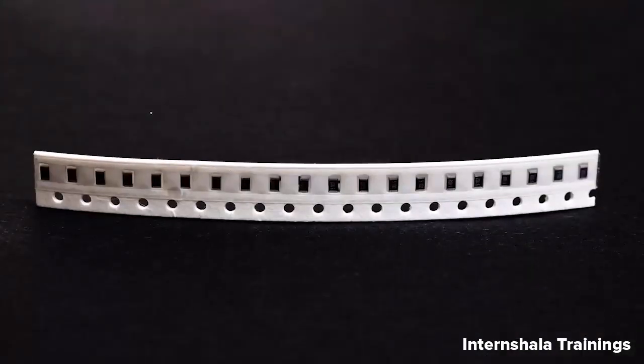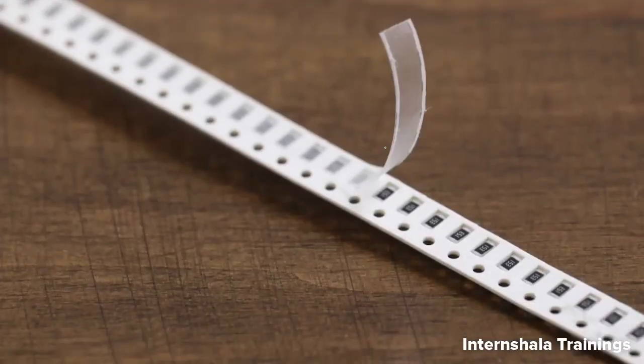After that, this is how you are going to receive the SMD resistors, and this is called cut tape. Why it is called cut tape, you will get in a moment. For example, if you order 20 or 30 quantity of SMD resistor, let's say 10 kilo ohms, this is how you are going to receive them. There will be a plastic film on top of this tape. You just have to remove this plastic film, and based on the requirement, you can take the SMD resistors from this tape. Now why is it called tape? Let me discuss that particular point.